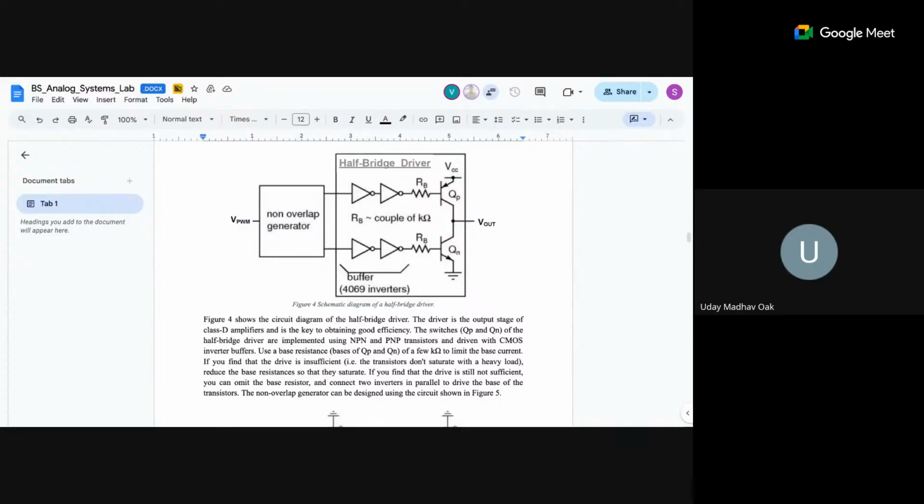And when it is PWM, when the transistor, either QP or QN, turns off, there won't be any alternate path for that inductor to release the remaining energy, right? If it had been MOSFETs, there could have been anti-parallel diodes, but in this case, it's not there. So do we need to add those? No, no, I think you're just complicating a simple thing. Just do whatever is being shown here. That should be enough. Okay, understood.